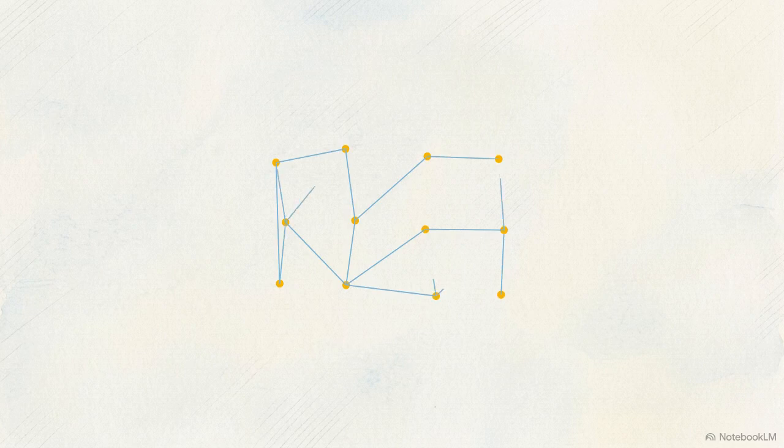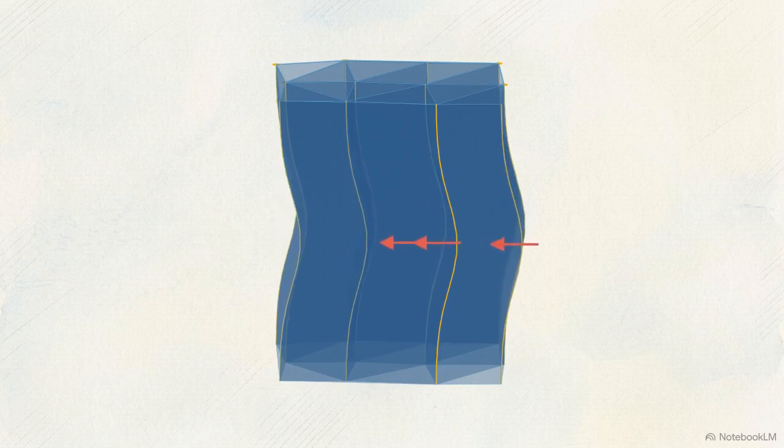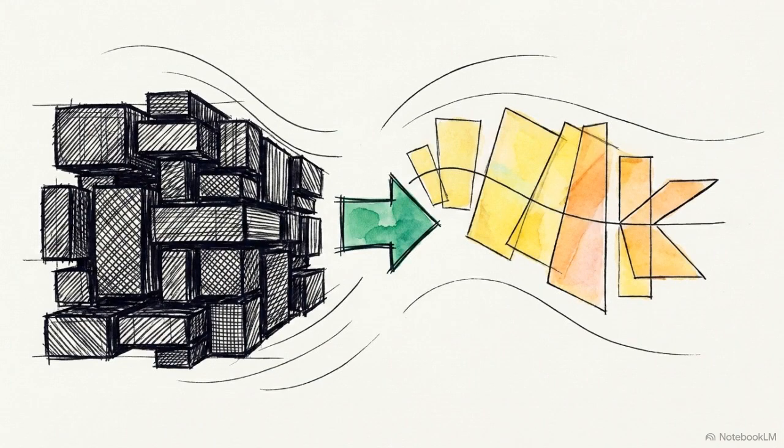Next, we replace the massive 3D matrix using 2D shell elements that dynamically link neighboring fibers. The process starts by calculating a Delaunay triangulation network across the cross-section, establishing a geometric web connecting the centers of every neighboring beam. The edges of this 2D network are extruded along the wavy fiber paths, creating interlinking quadrilateral surfaces. These 2D shells represent the surrounding resin matrix, providing the critical shear support that resists fiber buckling under compression. This shell beam dimensionality reduction drastically shrinks the total degrees of freedom, capturing the exact kinematics of mechanical failure at a fraction of the computational cost.